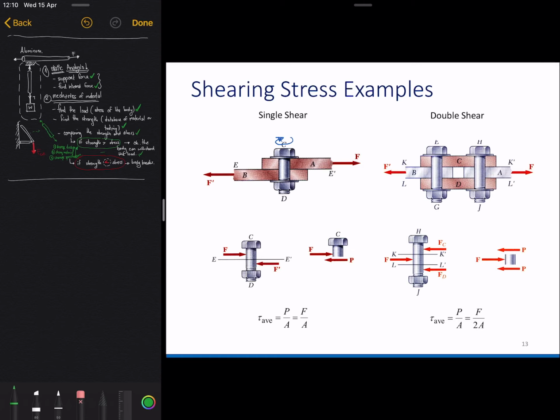The bolt will be in tension, and the bolt will elongate, and it still elongates within the elastic zone. Means it still has the force pulling back. Means when you tighten the bolt more, you create a tensile stress here,